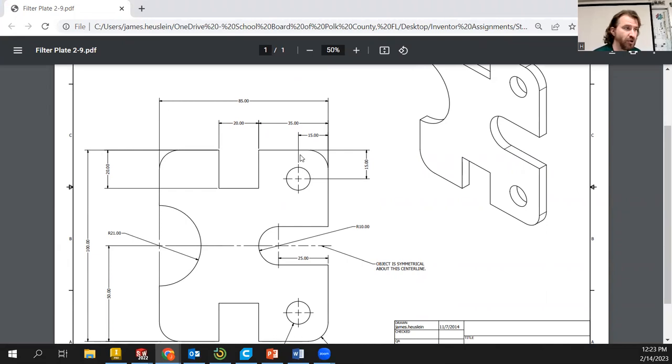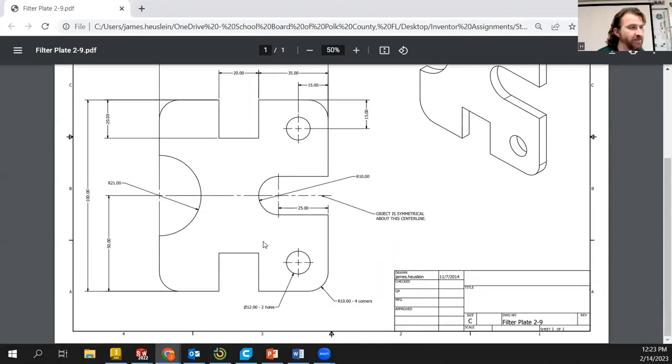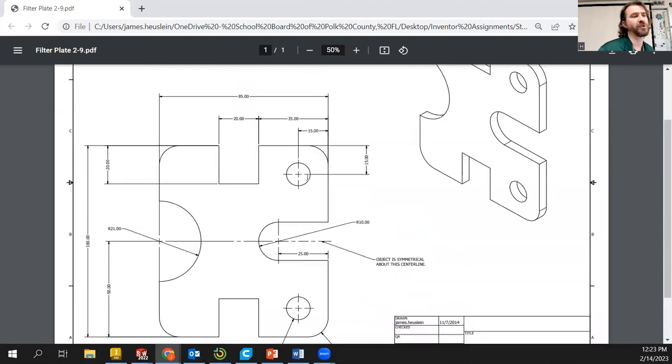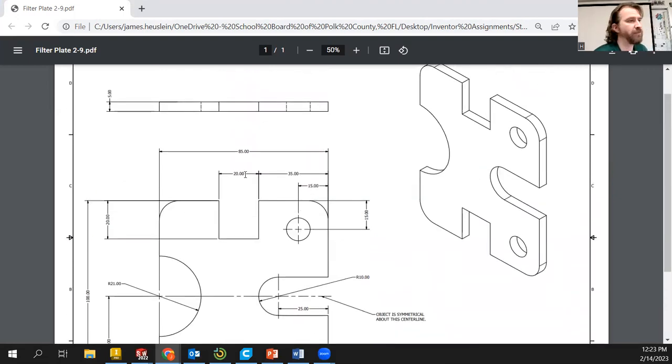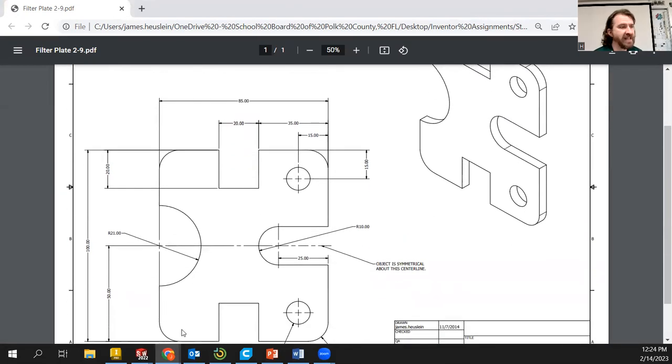We have the fact that there's a circle, the fact there's a half circle and arch right here, that there's half a slot. Right? We think of this as the slot tool, but there's nothing on the outside of the part. It's only on the inside, right? So we have a lot of visual information, circles, curvatures, etc., but also a lot of dimensional information or numerical information. Because we have the most on our front view, just like in the past, front view is where we're going to begin, making the outside perimeter first. Outside first, and then working on the internal components as we go.